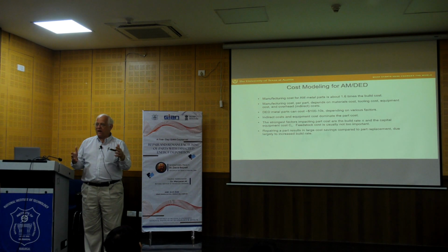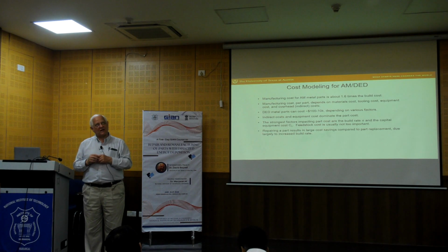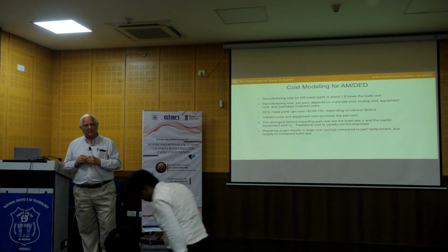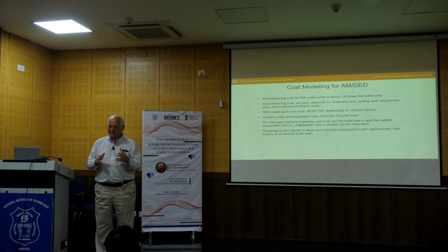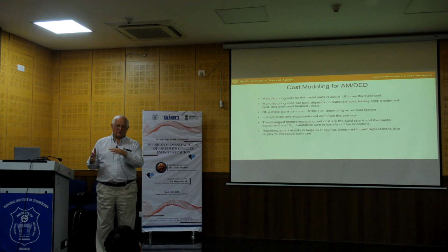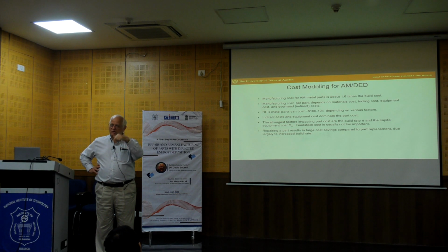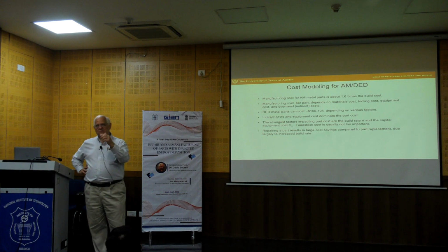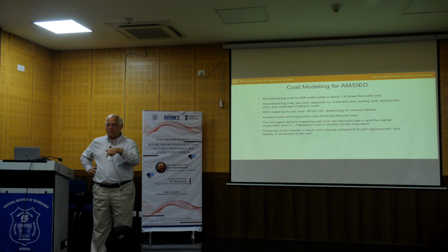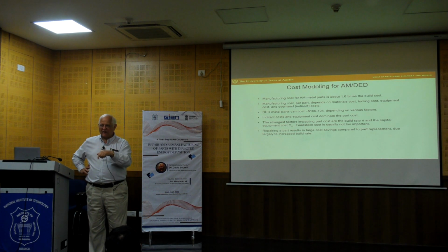In his case, he works with polymers, with nylon. You take a nylon powder bed, spread nylon powder, and then shoot down a dopant, which typically is carbon black, which couples highly to radio frequencies. They shoot down the dopant at the locations where the part is. This happens very quickly. It's a very fast process.